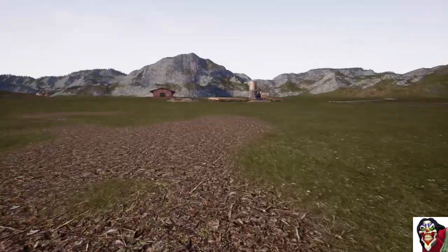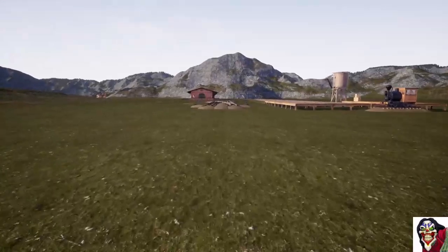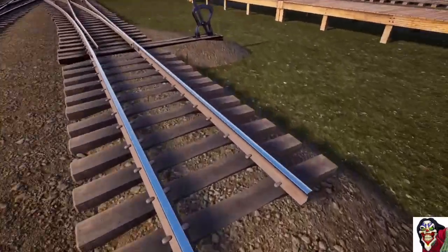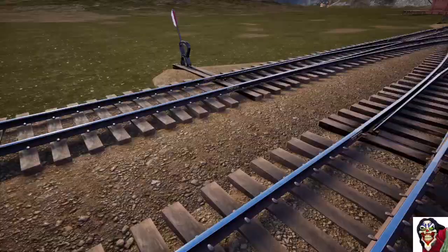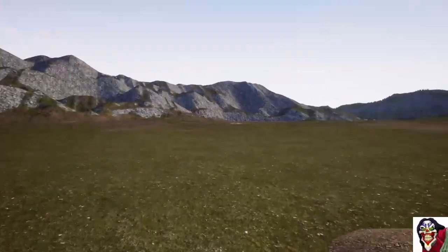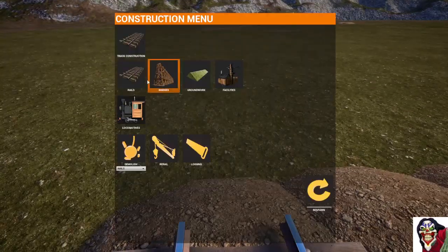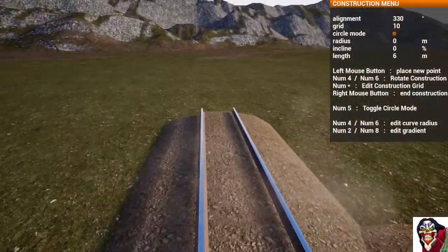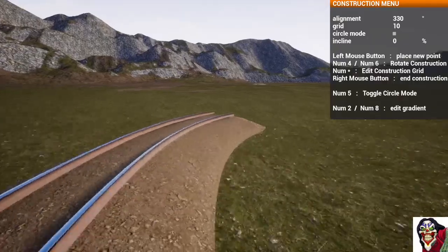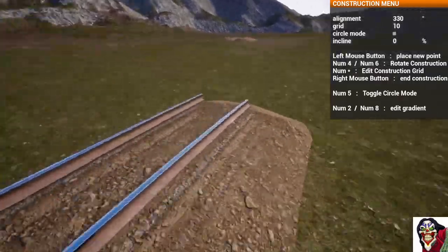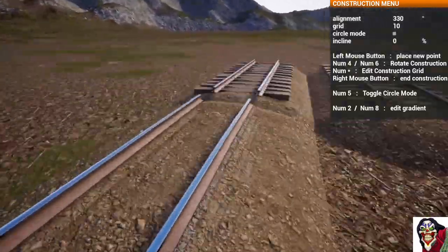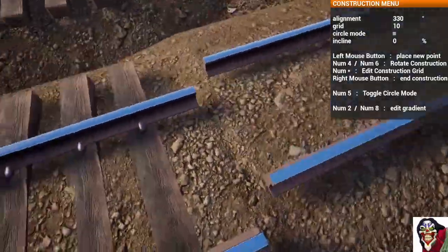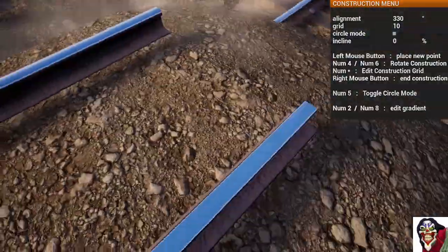So we will remove that bit which we used as the measuring device. Now all we have to do to put this curve in here is connect these two short pieces we made here over to those two short pieces over there, which is turn off circle mode. And we've already got the angle set for these pieces that we put in, so they'll automatically line up here on the end. And I have gotten stuck in the groundwork again.